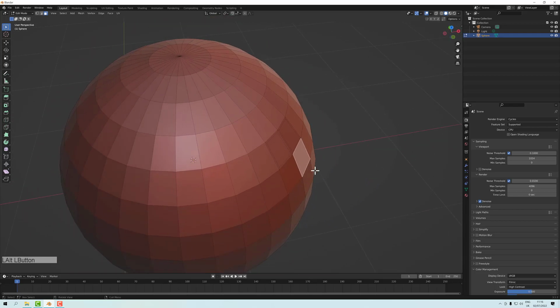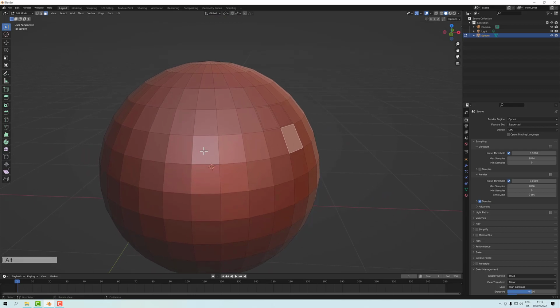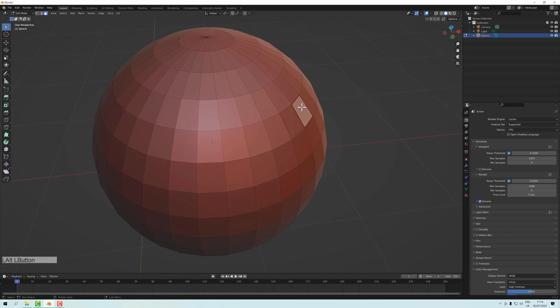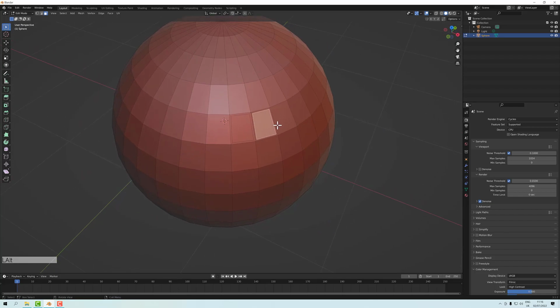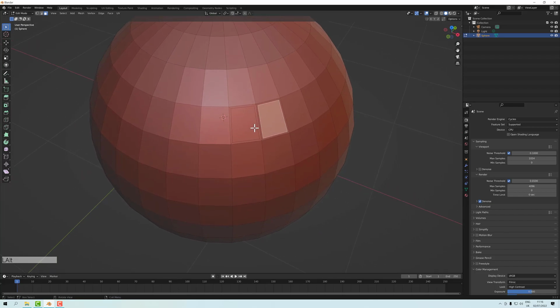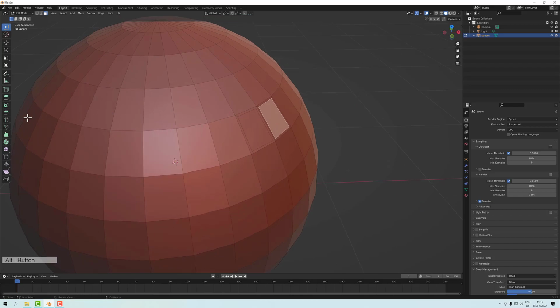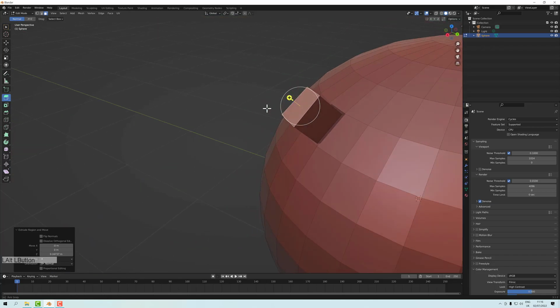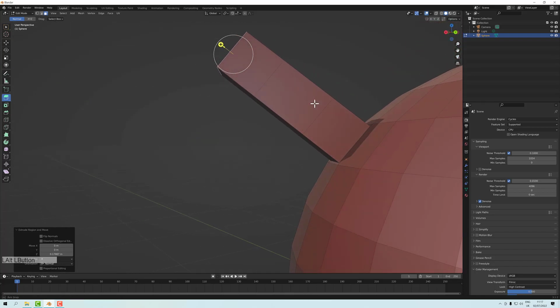Similarly, we have extrude options. So extrude will take that face and extrude it out along its normal. Well, that's one mode. So if you just click extrude here and then pull on this handle, it will extrude out. There we go. And if I stop and then extrude again and extrude again, it will add to that operation.